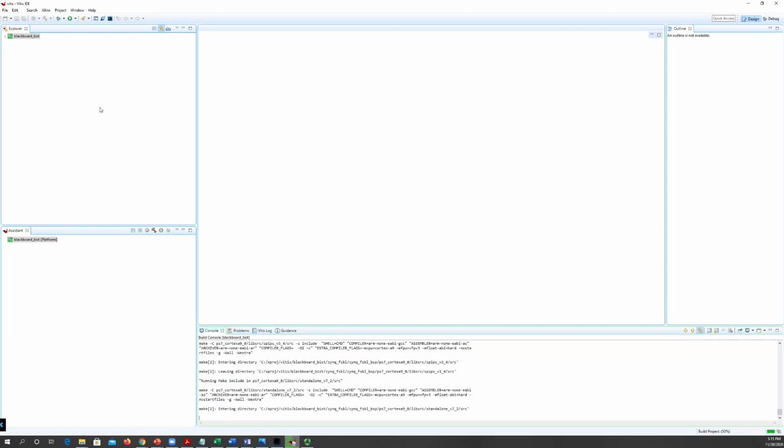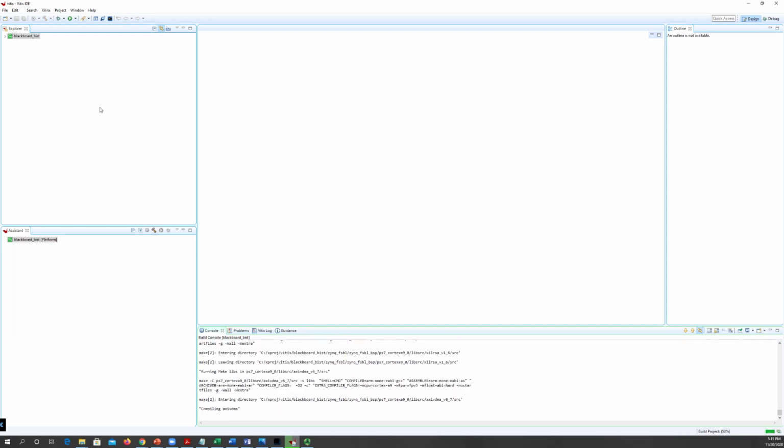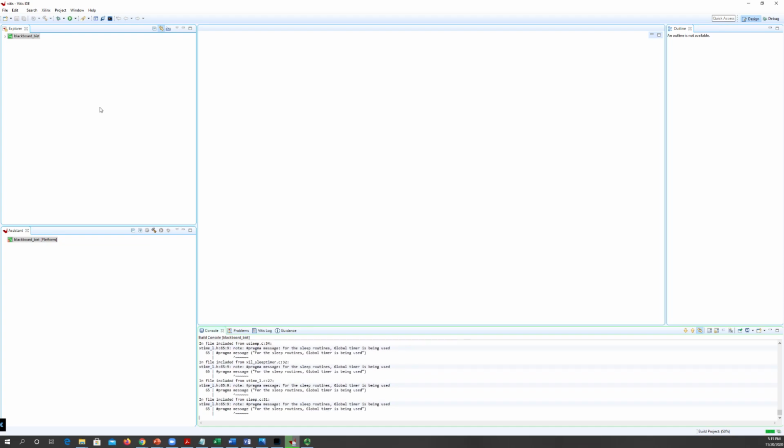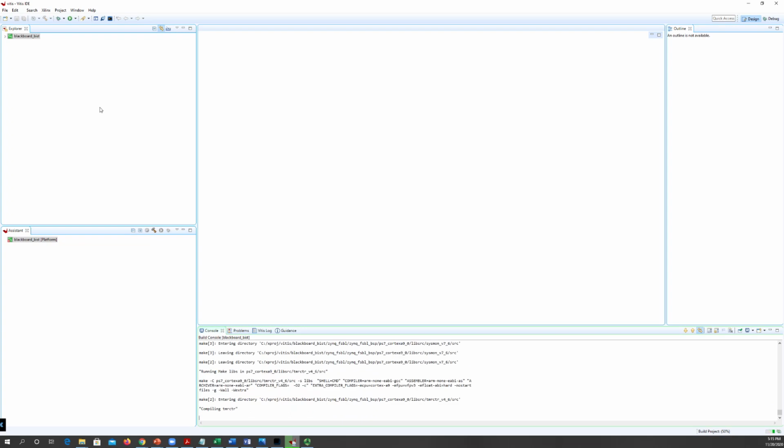There's an FPGA programming file that sets up the FPGA to map all of the buttons and switches through. There's a couple of other files too. There's the XSA file. That's the file that maps all the physical pin constraints. So which pins are connected to which devices, what their drive strengths are, all that kind of stuff. So this takes a few moments.